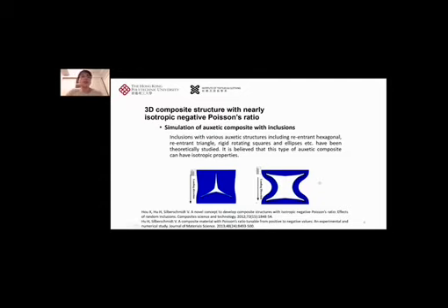So, in this figure, if you can see, these figures are from one of our previous works. We built this model of this reentrant triangle and the reentrant hexagonal in a 2D plane of some kind of material, just a plastic. So when we compress it, it can deform and contract in the lateral direction, which shows the auxetic effect of this overall structure. So inclusions with various auxetic structures, not just this reentrant triangle and reentrant hexagonal, but also rotating squares, ellipses, etc., have been theoretically studied.